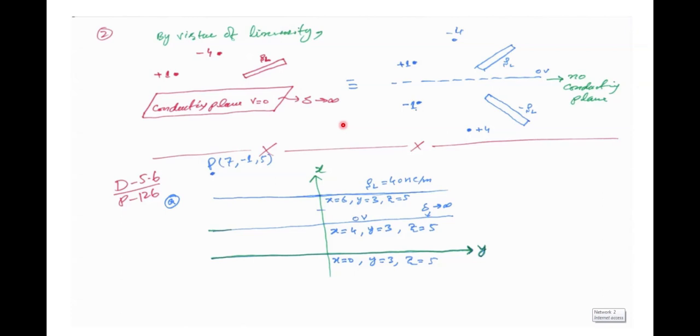When any radiating structure is located above the surface, we remove the Earth's surface by locating the image of that radiating structure, and that way it is very easy to define the potential or the electric field due to that radiating structure.